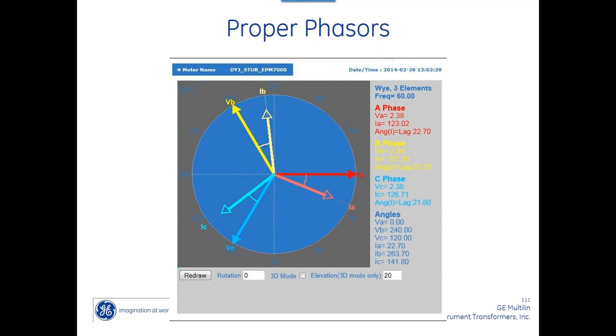While y'all are thinking about it, I'm going to answer this question. I personally don't like split core CTs because you're breaking the connection on the iron core and it does not give you as good an accuracy. Somebody said ABC. I want somebody else to say ACB just so we're going to have an argument.